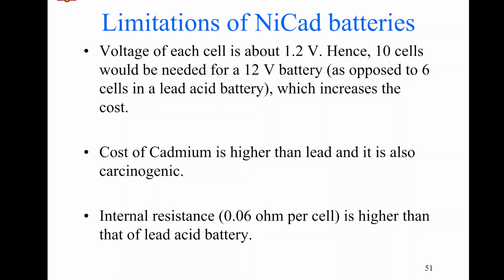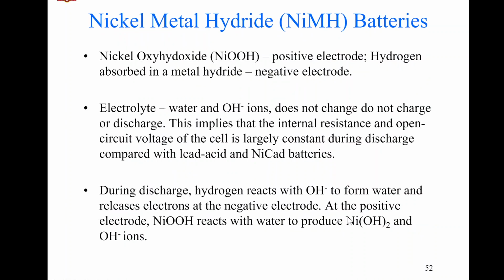Moreover, the cost of cadmium is higher, and it is also a carcinogen, and it also has higher internal resistance of 0.06 ohms as opposed to 0.02 ohms in the lead acid batteries. Then taking a look at